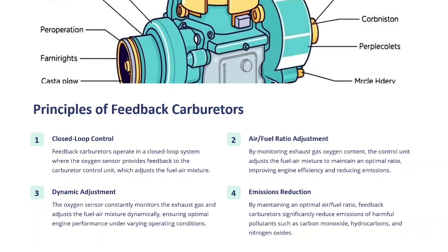It means monitoring airflow and fuel flow rates, adjusting the fuel injector pulse width and the airflow to maintain the ideal air fuel ratio for ensuring the proper fuel optimization and mixing for efficient combustion.